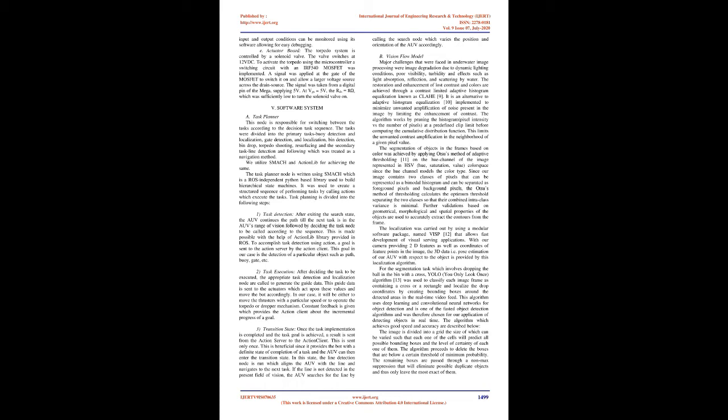DC-DC NUC is a dedicated power source which supplies a constant uninterruptible 19V output to Intel NUC. It has many programmable functions that allow it to turn the NUC off when inputs fall below certain thresholds. Additionally, the input and output conditions can be monitored using its software, allowing for easy debugging.